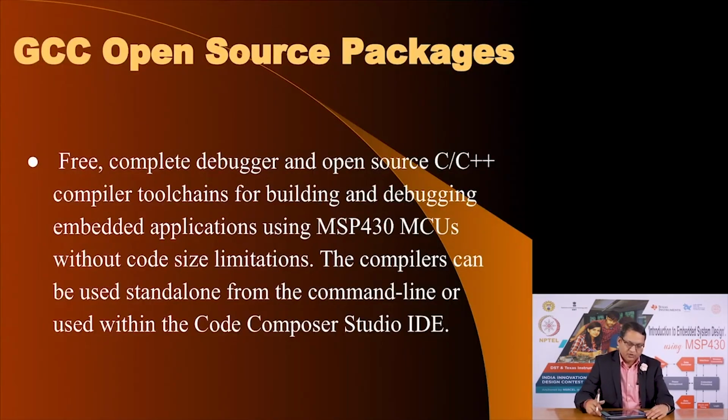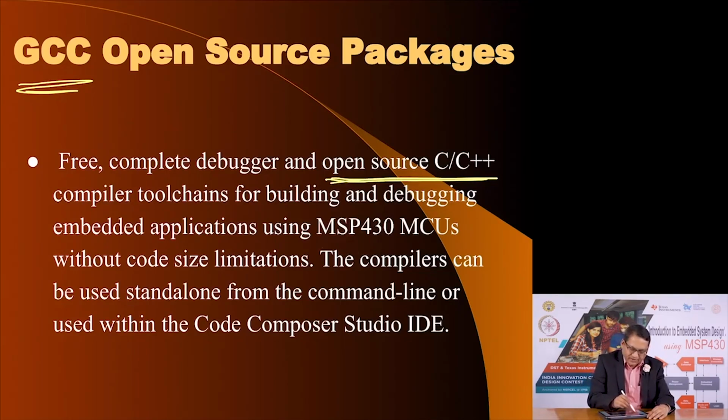Apart from all these options, you can also use GCC mechanisms, which use open source packages, a free complete debugger, and open source C++ compiler tool chains for building and debugging entire applications from scratch to finish around the MSP430 microcontroller. Oftentimes this works on a command line, and one of the advantages of the GCC tool chain is that it does not have any code size limitations.